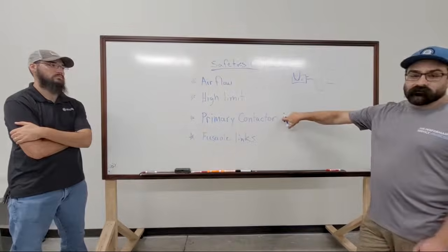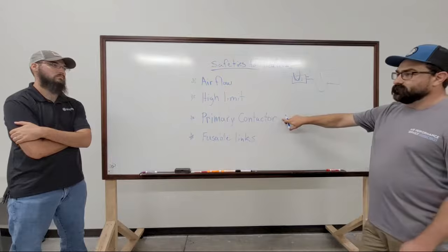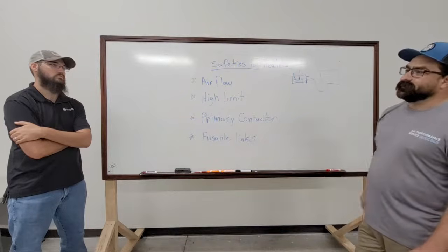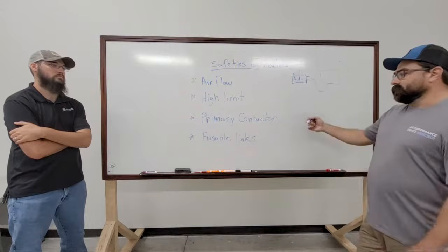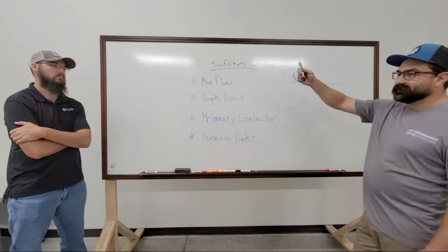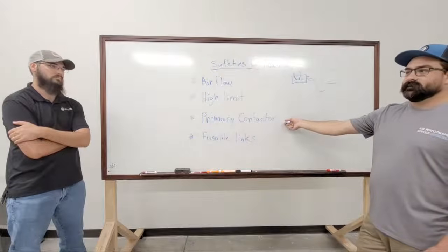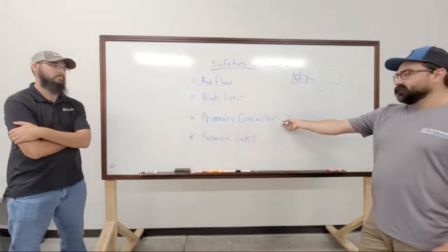This one throws people for a loop because they're like, oh, my contactor's not pulled in. Why not? And they just don't understand why. And then even when that contactor pulls in, the heat doesn't come on, or this contactor pulls in as soon as the fan starts up, and they don't understand why. They think this should be off.